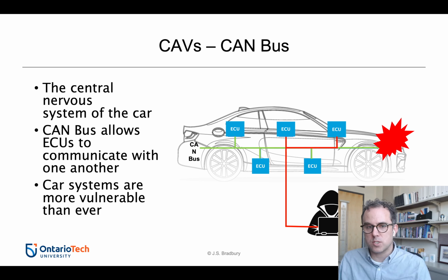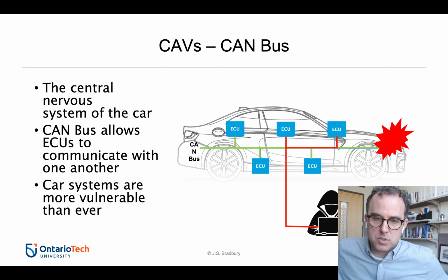You also have to think about challenges when you're using standards, like I mentioned Bluetooth earlier. Well, there are actually potential exploits in Bluetooth. So depending on the version of Bluetooth, they may be trying to utilize a known vulnerability in the Bluetooth, right? Now, here's a good thing about that: the Bluetooth is through the infotainment system. And in many vehicles, the infotainment system, because it is what you typically connect your phone to and other devices, has restricted access to the CAN bus. They may have it set up so data can only be received by the infotainment system, not sent from the infotainment system to other components.